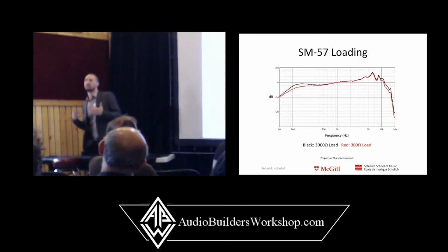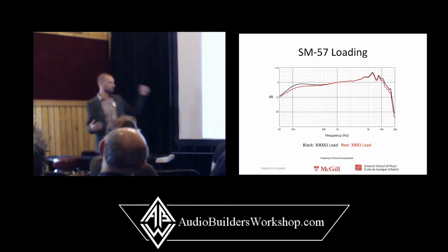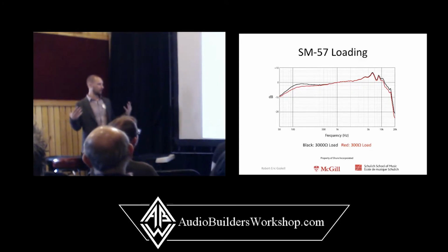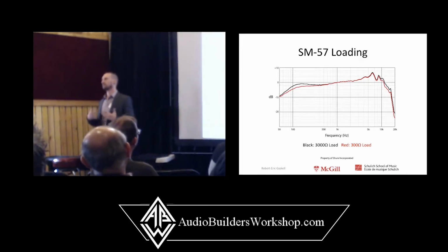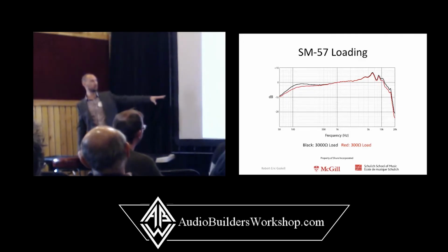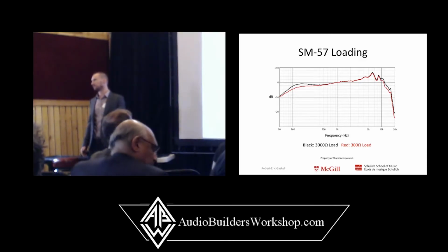The Grace has a very high input impedance, around 6K, so it's going to accentuate the low end and also accentuate the high end, for me, in a not necessarily pleasant way. So matching the particular microphone with the particular input characteristics of the mic pre is an important aspect of the sound of the mic pre itself.